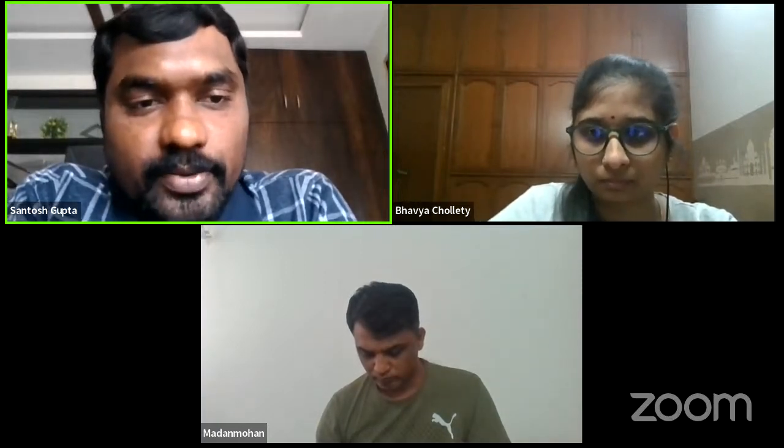And there's a question from Vikram. Hi, sir. Where to place SVC and StatCom in the system, and what is the cost? Basically, as I told in my presentation, at the PCC point we need to limit the harmonics as specified in the IEEE 519 standard. So what I will do is always try to place an SVC or a StatCom very close to the source where I would like to reduce the harmonics, basically on the medium voltages in the system.